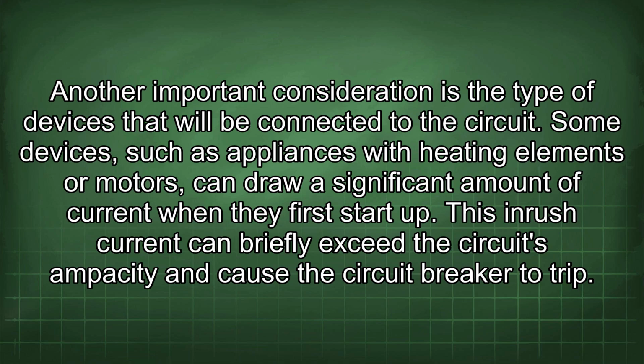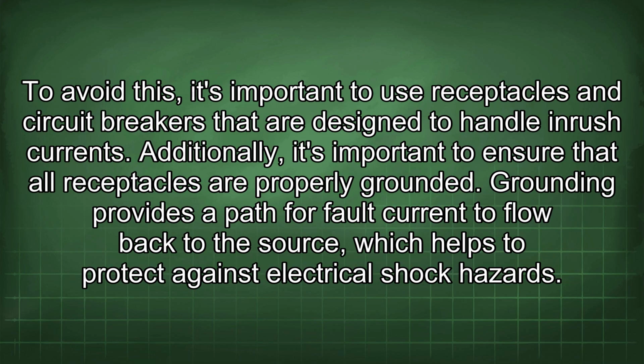Another important consideration is the type of devices that will be connected to the circuit. Some devices, such as appliances with heating elements or motors, can draw a significant amount of current when they first start up. This inrush current can briefly exceed the circuit's ampacity and cause the circuit breaker to trip. To avoid this, it's important to use receptacles and circuit breakers that are designed to handle inrush currents.